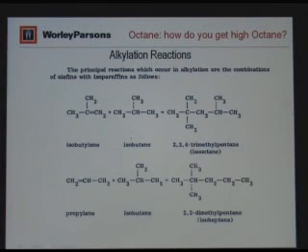And these are the basic alkylation reactions. Isobutylene, isobutane to isooctane. Sounds very simple, but again, it's a reaction. And a reaction has to be carefully controlled because you may want to combine a C3 and a C4, but if you overdo it, you'll end up with a C20 or a C25 because they just keep adding and adding. So you have to control the reaction conditions very carefully. But there are basically two processes. One uses sulfuric acid, the other uses HF, hydrofluoric acid.